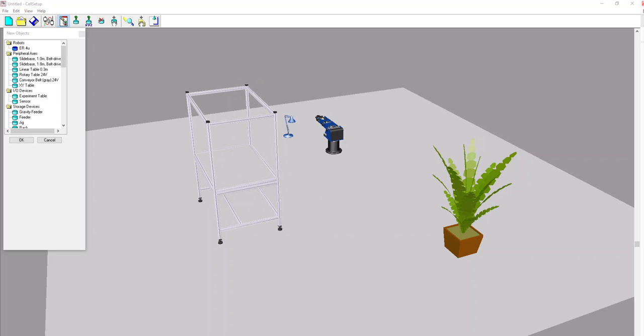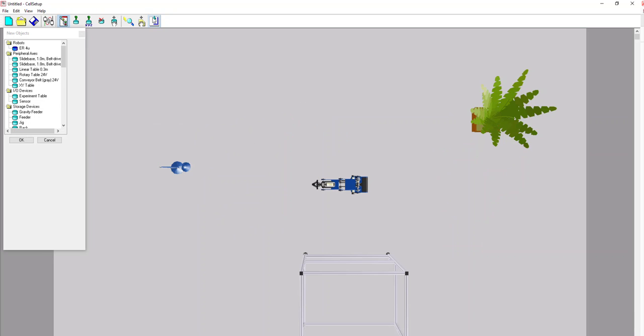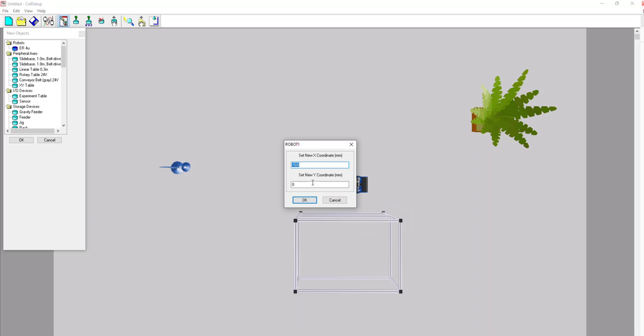And the best way to move your objects is first to switch to the top view. So here is easier. You can see the top view, you have one dimension. You still can move your car. So this is one of the options. You can move the base or the table to where the robot is. But in order to position your robot, again, you double click, and you have the position.